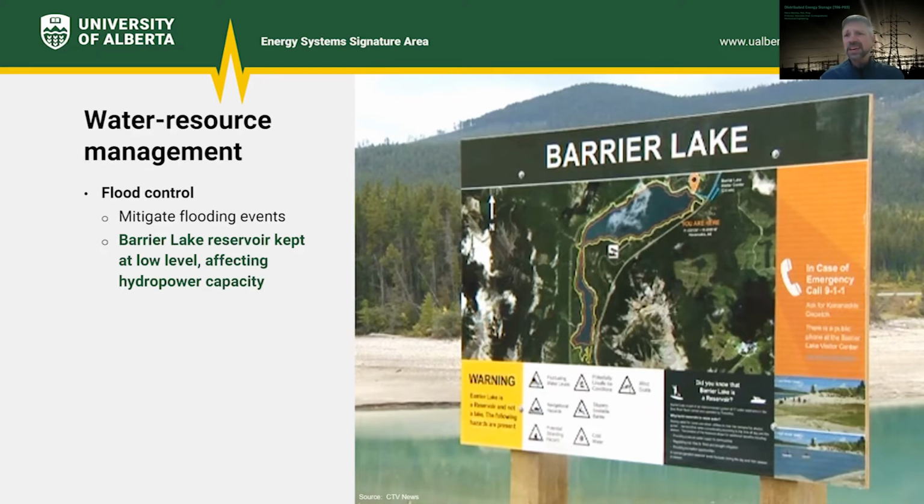We want to be able to catch as much water as we can, so to give us time to mitigate the flooding that will potentially come from this major rainstorm. So therefore, nowadays, Barrier Lake is actually kept almost empty. If you go up to Barrier Lake right now, you will see a lot of gravel, little water. That lake is actually almost empty, and it really affects the hydropower capacity that we can produce from that particular power station at Barrier Lake. So one constraint I didn't know, flood prevention, is a big one.